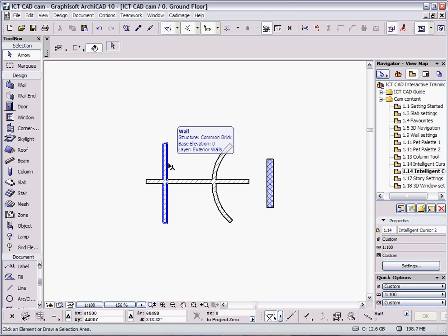because in the case of walls, walls have a reference side, so the reference side always shows with a bolded Mercedes icon. And we can actually see that with the pre-selection preview that we're seeing at the moment with the blue lines. If I go over the horizontal wall, again that tells me that's the reference side, whereas the opposite side is the inside typically, and that shows the thin Mercedes icon.